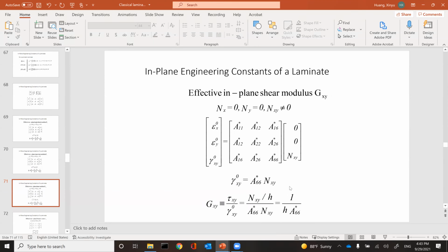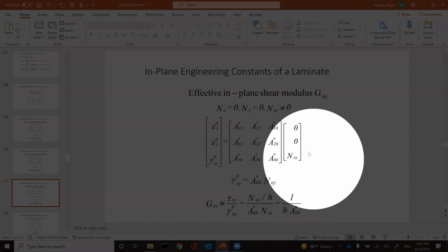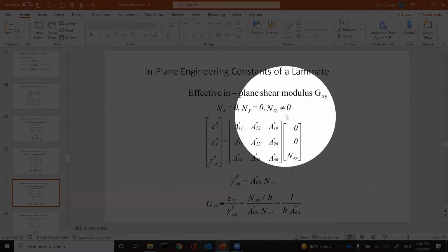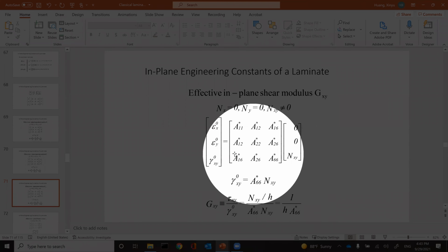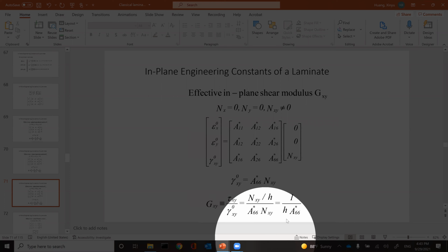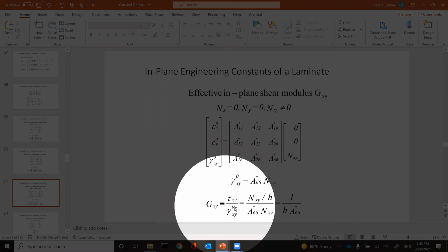And you can do shear modulus. The equivalent shear modulus of the laminate. It's a very similar case. You again imagine there's a test done this way. You apply shear load, and that's a shear strain, and then the ratio of them is the shearing modulus.